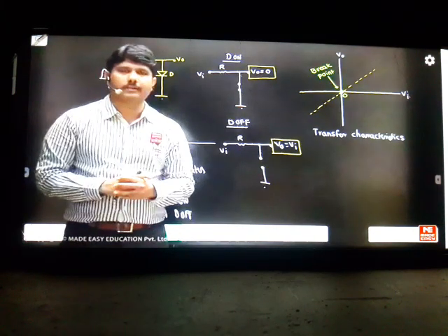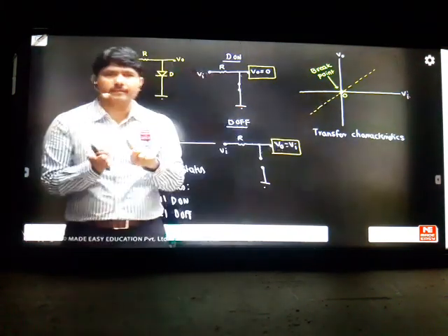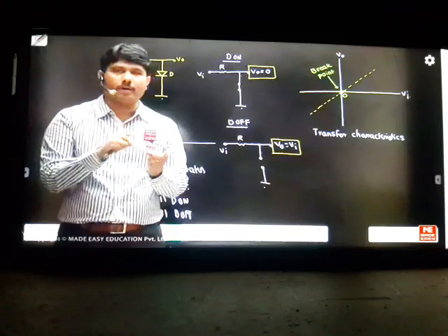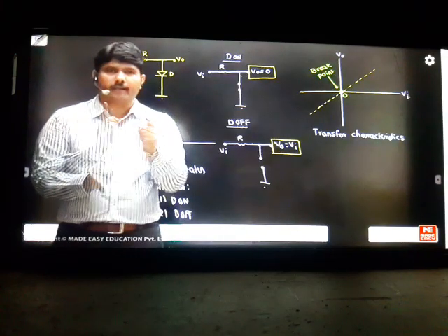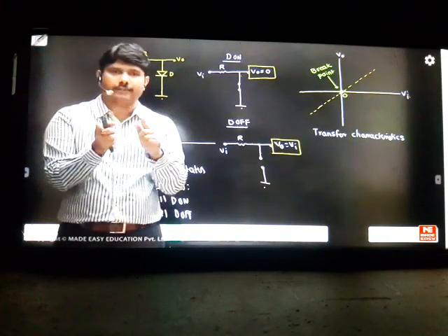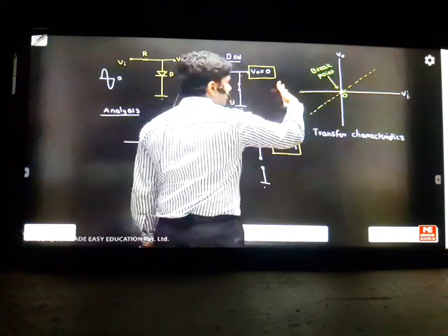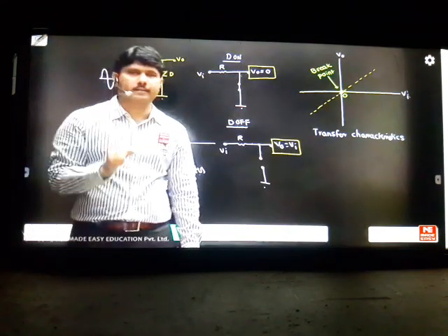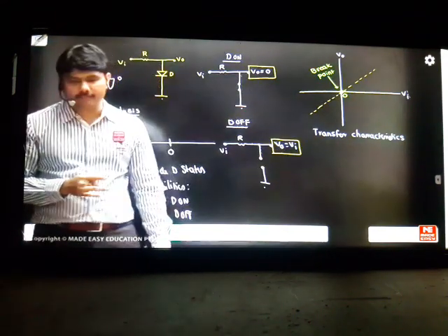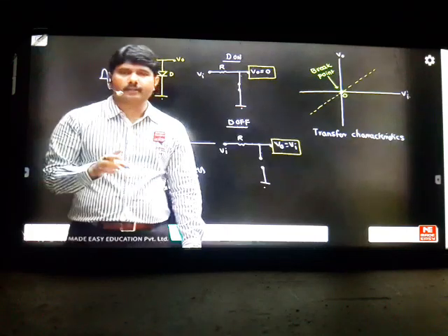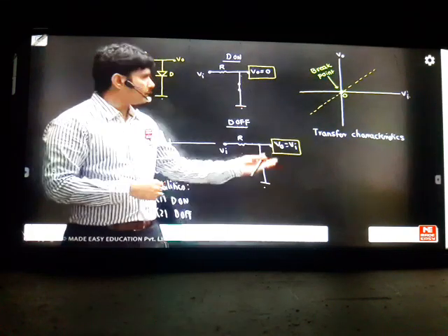The advantage of understanding the break point is that below this break point the switch can be on or off, and above the break point the switch can be on or off. Possibilities are there. So that point will decide how the characteristics of the graph change. Below, the switch is working in one manner, above it is working in another manner. That is decided by the intersection point called the break point. Therefore it is very convenient now. For single diode problems it's very easy. Just one diode means on or off, and you just find these lines.